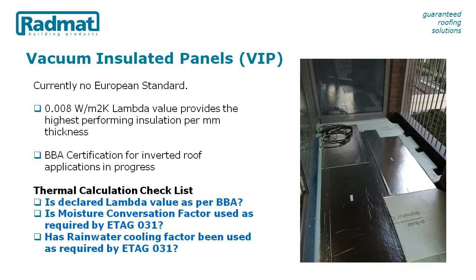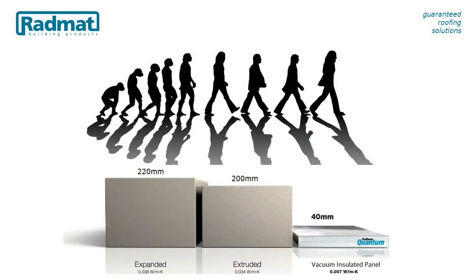Above 20 floors, it may be possible to gain an extra floor, and on most projects, its use on small areas only has minimal impact on overall roofing cost. Most beneficial is the ability to comply with the thermal requirements of Building Regulations Part L, the access requirements of Building Regulation Part M, and the drainage requirements of NHBC Chapter 7.1.